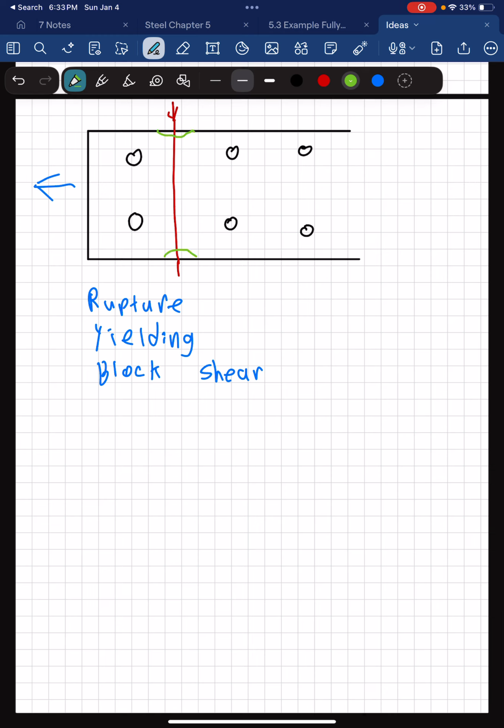And if any of you have taken a strength of materials class or a material science lab, you may have done a problem with, I can't exactly remember what it's called, but basically you get a test blank that looks something like this, and you're going to put it into a machine, and you're going to pull it, and then you're watching this section right here to see when it yields or even completely snaps. And that yielding is when it starts to neck and pull apart. So these two start to pull apart, and you'll see that the strain starts to deform the material.